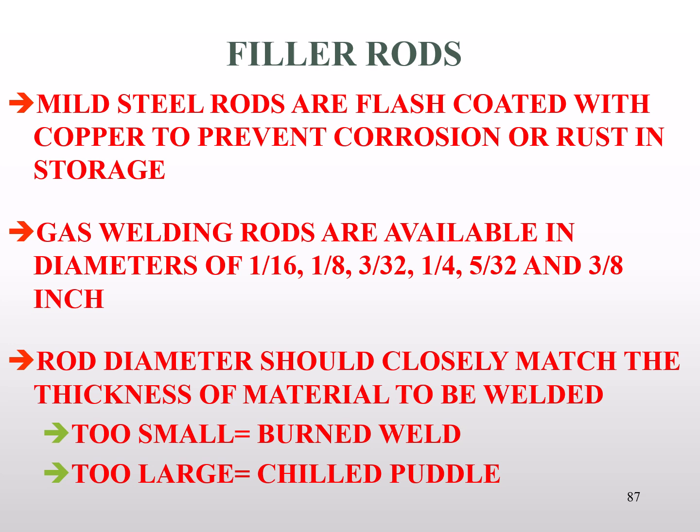Now, these filler rods come in different sizes, from 1/16 on up to much bigger around than that. These diameters vary, and there's a simple rule. Match your filler rod thickness with the material thickness of the weld you're going to make. So once I know my material thickness, I can select the right rod.